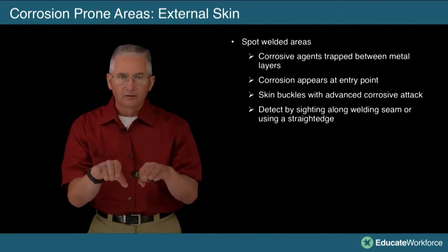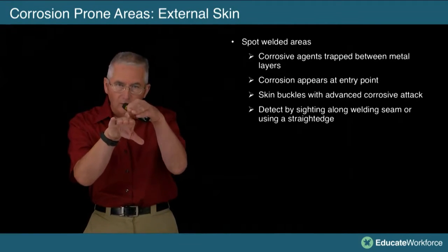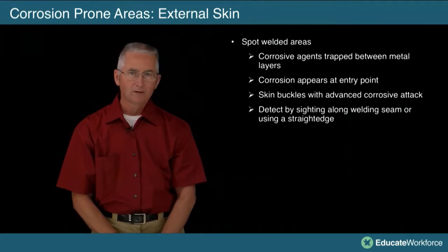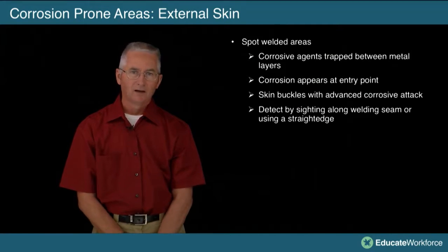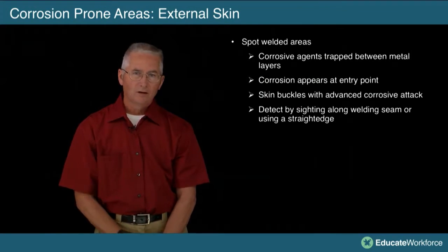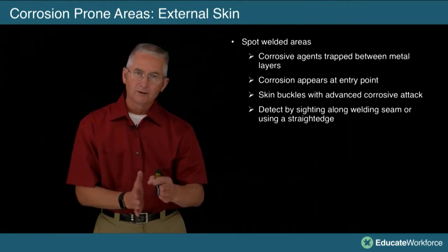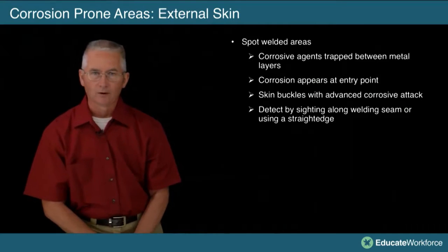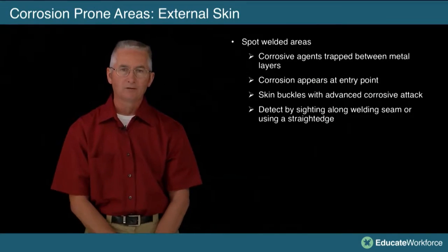Looking across, sit at the edge of that wingtip and just kind of look towards the fuselage. Notice and see if you've got any ripples. Maybe you want to get a straight edge out and put it on there. Again, you're looking for stuff that doesn't look the same. I'm looking for something just out of the ordinary. What catches my eye? And then focus on that right there.